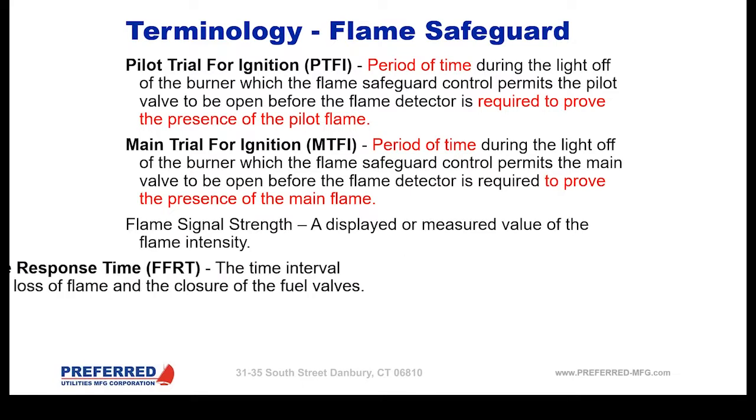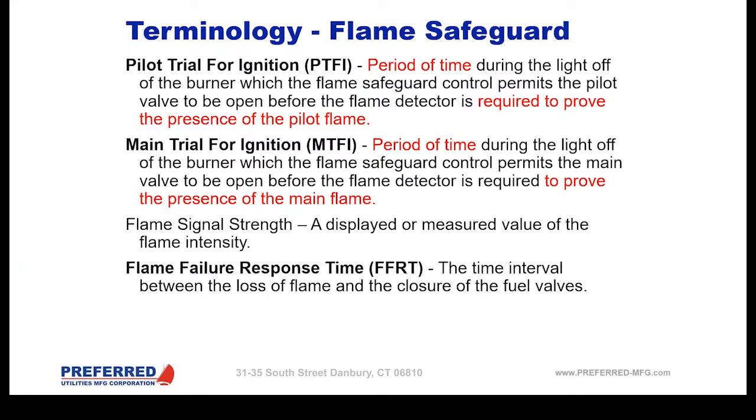Flame failure response time, also a very important term. This is the interval between if we were up and running, for instance, and all of a sudden our flame detector was not giving us a flame signal. It's the amount of time from the time it loses flame signal to when we shut all the fuel valves and go into a lockout condition. That's what the flame failure response time is.